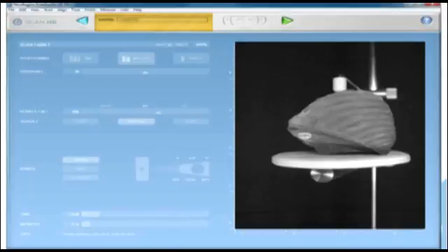You can adjust, as you can see, the resolution, points per square inch, as either a quick low resolution, a standard, or a slower high resolution scan. You have to set the target color. It needs to know whether it's a dark or a light or a medium color. You also need to set the range, and then at the bottom it gives you an estimate as to how much memory the computer will require and how long the scan will take.